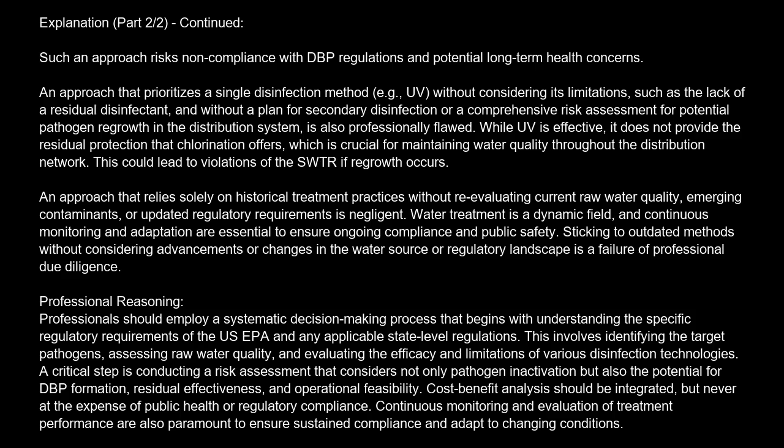An approach that prioritizes a single disinfection method, e.g., UV, without considering its limitations, such as the lack of a residual disinfectant, and without a plan for secondary disinfection or a comprehensive risk assessment for potential pathogen regrowth in the distribution system, is also professionally flawed. While UV is effective, it does not provide the residual protection that chlorination offers, which is crucial for maintaining water quality throughout the distribution network. This could lead to violations of the SWTR if regrowth occurs.